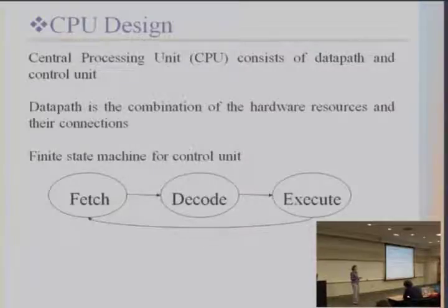That would be our fetching state. We are loading the instruction into instruction register, so now we can perform that instruction. What is the instruction? Well, the code will tell us that. We have to read these bits and figure out what is our instruction, and then we need to execute it, which is the rest, like adding these two registers into third register.